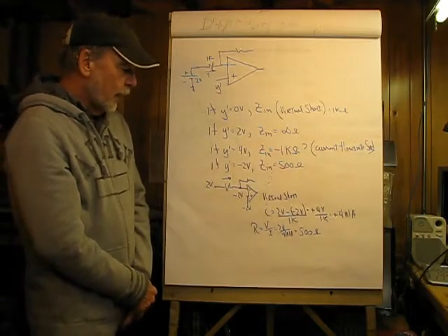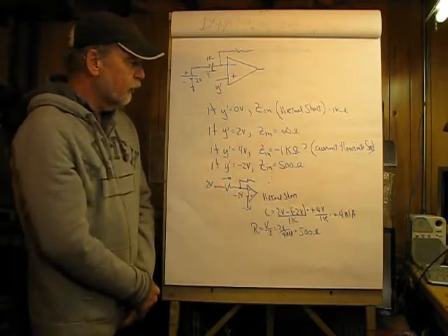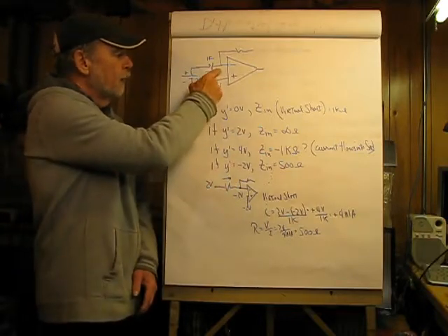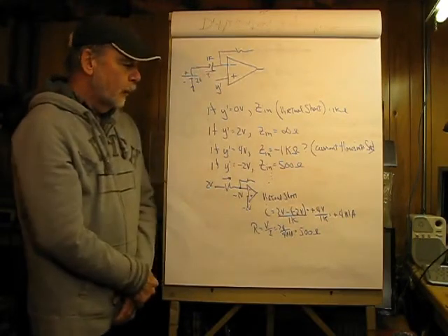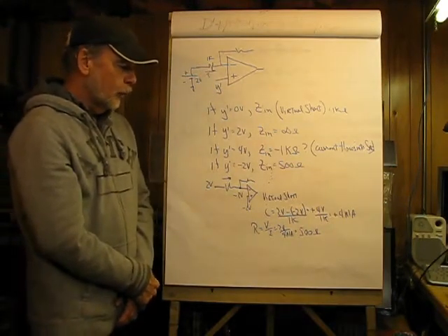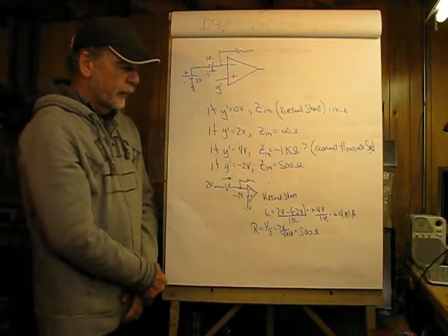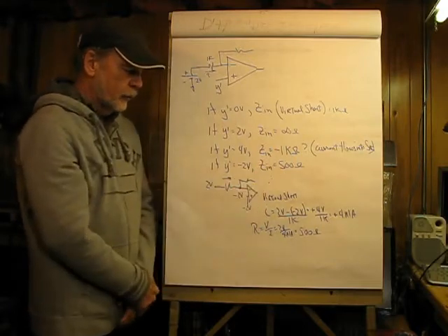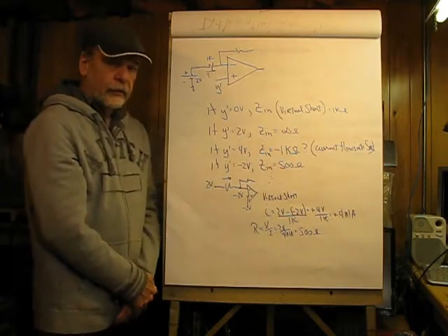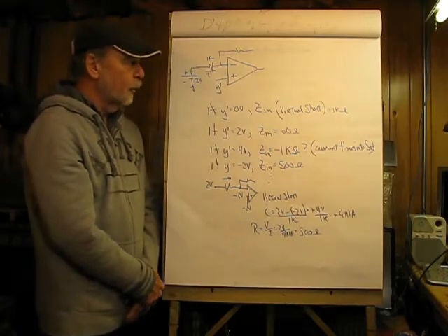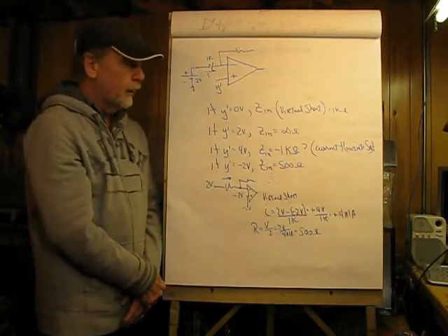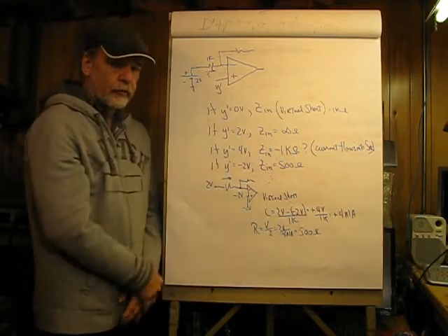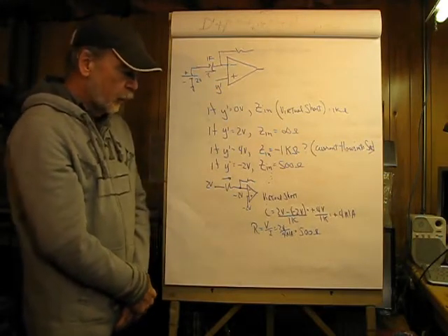Finally, if y prime equals negative 2 volts, that would be 4 volts across this. The drop would be plus to minus. We would have 4 milliamperes flowing, and the resistance would end up looking like 500 ohms. So what we can see here is that the input resistance of this leg varies tremendously, and it's a function of this voltage. That's not really a good thing.